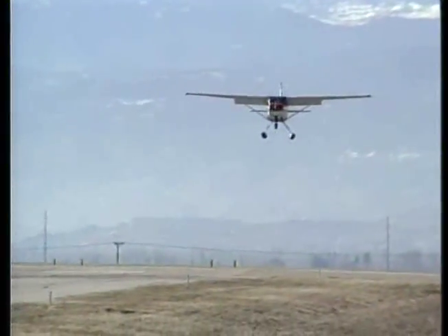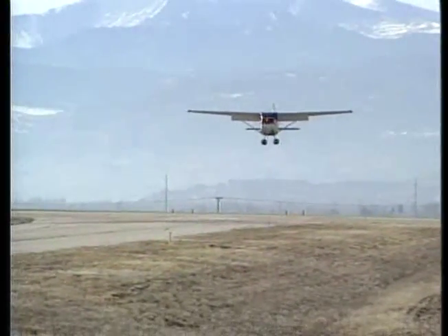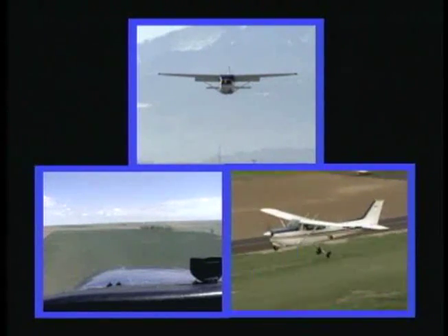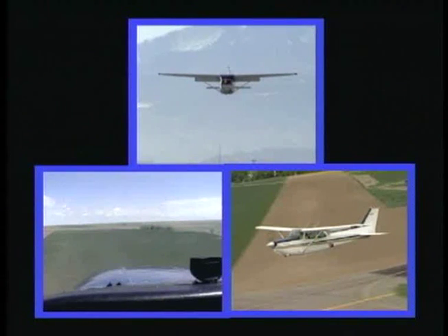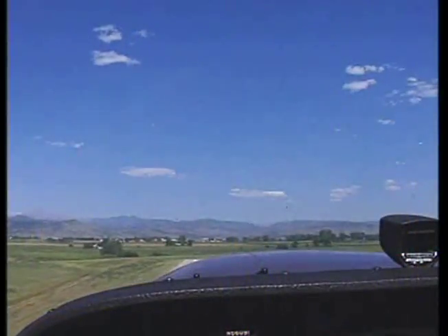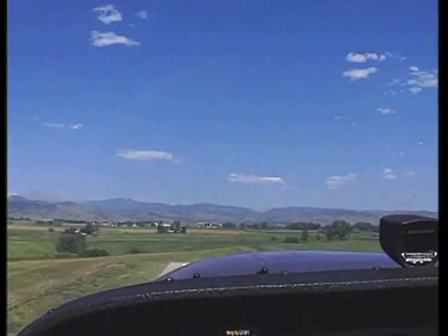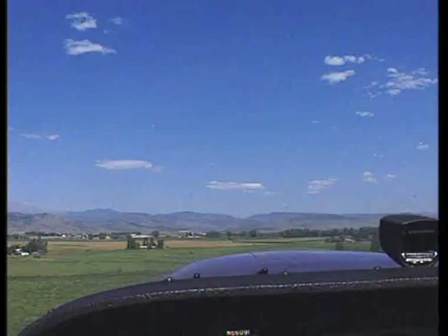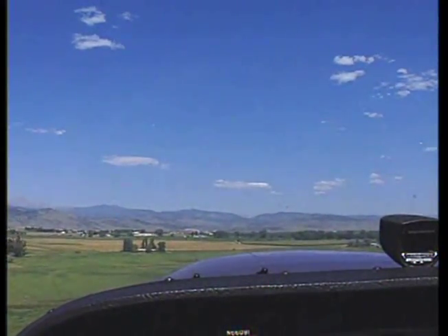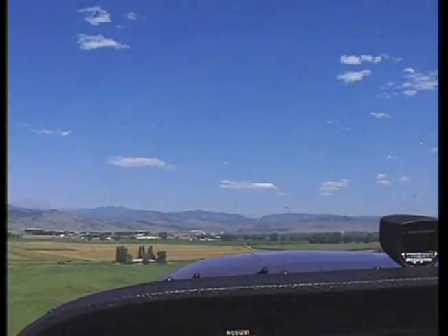It is imperative that a stall does not occur when full power is applied during a go-around from a normal landing approach, a simulated forced landing, or immediately after takeoff with an improperly set takeoff trim setting, because the amount of pitch change and altitude needed for a recovery may be inadequate. From this demonstration, it is apparent that stall recognition is important, and prompt recovery procedures should be implemented immediately to prevent a fully developed stall condition.